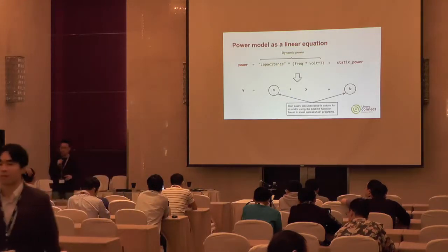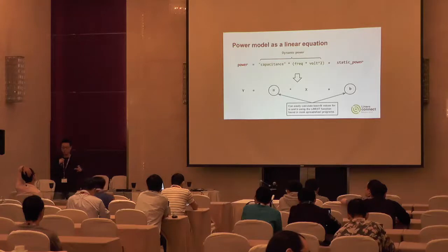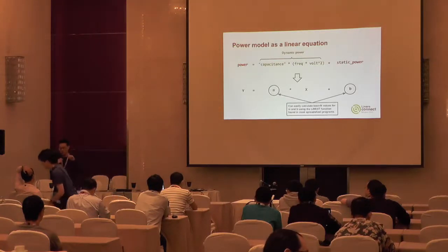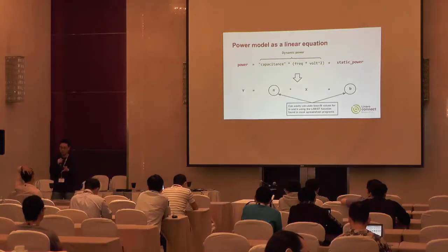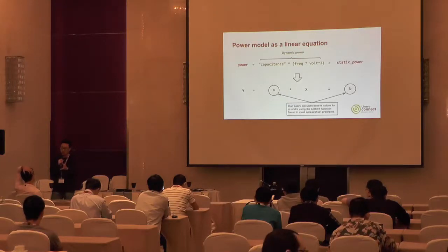But some SoC vendors may have a specific power state that disables the clock to the cluster level while still keeping the cluster powered on, so they can measure the static power.